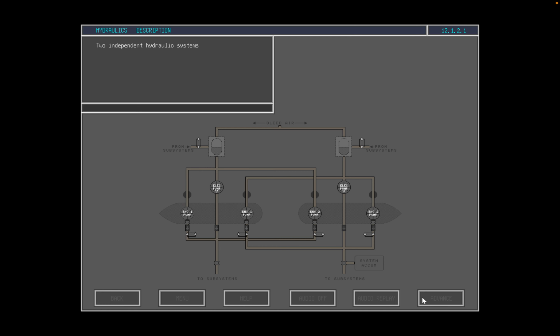The supply of hydraulic power to aircraft subsystems in the Fokker 100 comes from two independent hydraulic systems. These systems are identical in performance, but differ in capacity. Hydraulic System 1 has a reservoir capacity of 23 litres, and System 2 has a capacity of 4 litres. In addition to the separate reservoir supplies, each system comprises 2 engine-driven pumps, each equipped with fire shut-off valves, a low-capacity electric-driven pump used mainly for maintenance purposes, and a system accumulator.